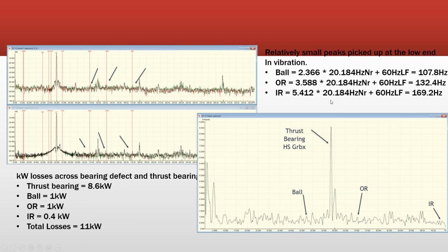They called back and kept telling me, well, you're wrong because it was actually turning at 1300. Nope, it's turning at basically what amounts to, I think this was 1218 RPM constantly. But the tach says, nope, it's turning at that. And the reason it's turning at that is because the magnetic field is turning at that speed. Otherwise, I'd have something other than 60 Hertz. And I can actually use my line frequency to give me an idea of where I am with that frequency.